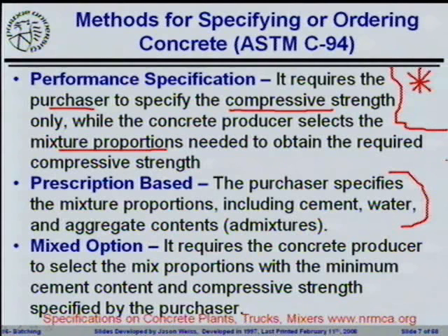I think this is a little bit of a trickier way to go in the prescription spec, and you're seeing a lot of people move away from this. It's great in an area where you don't have a lot of experience. However, it really loses out on allowing people to really optimize their overall process. What you'll see very frequently is the idea of mixed options, where the concrete producer will be asked to select their own mixture proportions given certain requirements on cement contents or requirements on compressive strength, things like that.